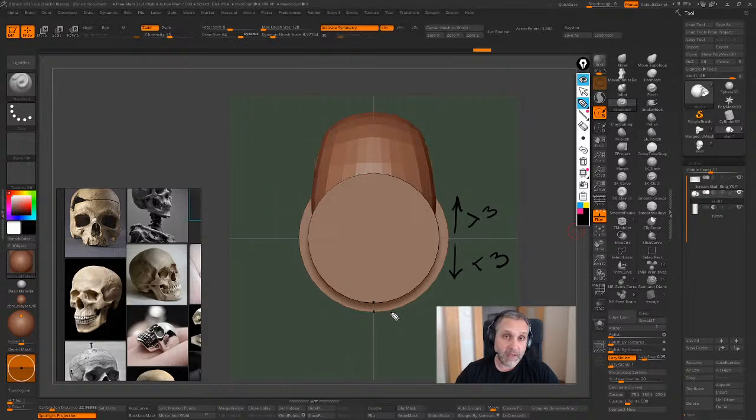So the thinner you make it, the lighter it will be. So depending on if you are going to use gold or silver, you can go around 2 millimeters instead of 3, which will be better for the weight. So try to find a good balance between the wearability and the weight, and of course the final price. But here at the bottom I try to keep it around 2.5 millimeters, trying always the same rule, less than 3 millimeters, more or less.